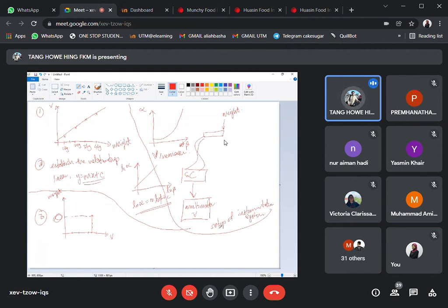So after you have set up the instrumentation system, at step 3 we are actually trying to determine the accuracy of your instrumentation system. So in this case, we are going to apply some kind of unknown load. So let's say maybe again we use a standard load, a standard weight. Let's say this is 1 kilogram.